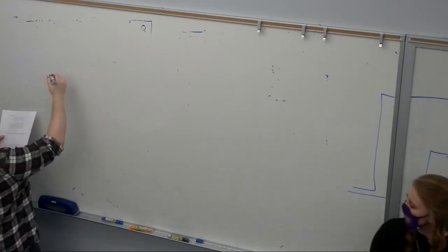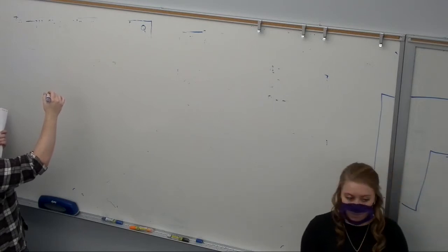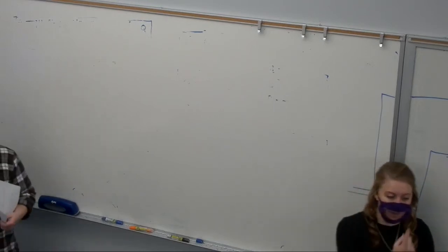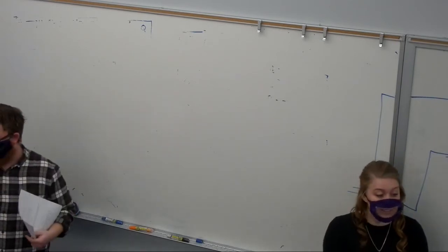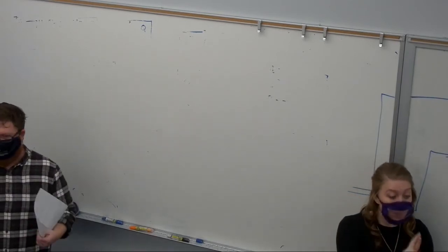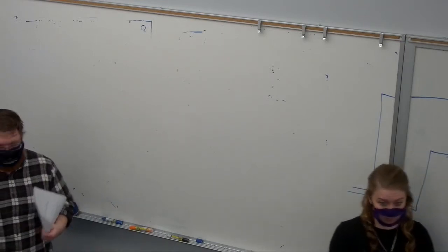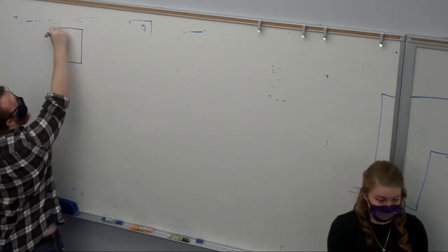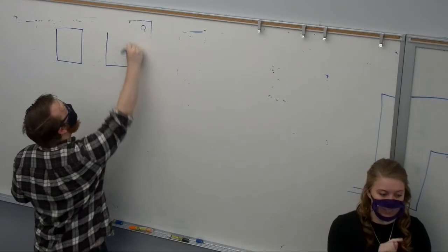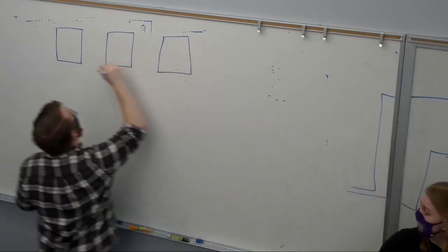So one form of, I want to figure out if I want to do this as an up or down counter. Let's use this same principle to build an up or down counter, right? So we talked about up counters and we talked about down counters. Let's build one that is either. Okay, so we're going to use T flip-flops because in my opinion, those are the easiest ones to build counters out of.